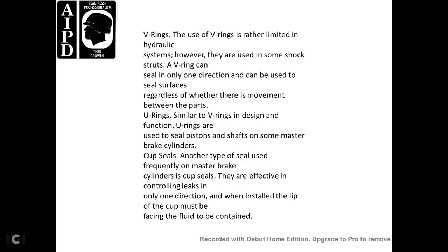Cup seals. Cup seals are another type of seal used frequently in master brake cylinders. They effectively control leaking in only one direction. When installed, the lip of the cup must be facing the fluid to be contained.